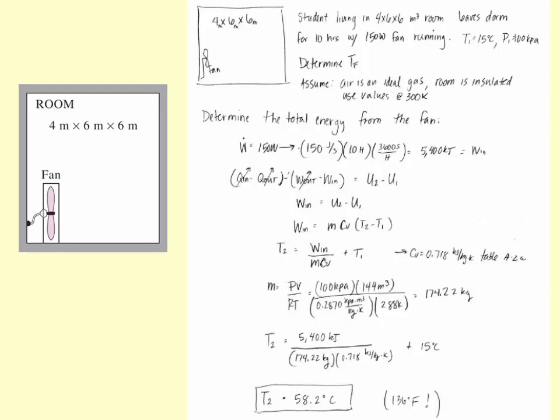Okay, so we can use the equation for specific heat. We could, using T1, go to the table and look up U1. But we are trying to find T2. We don't know that value, okay? So we might need to use some average specific heat in there. Okay, there's a couple different ways to solve this problem. What is U?